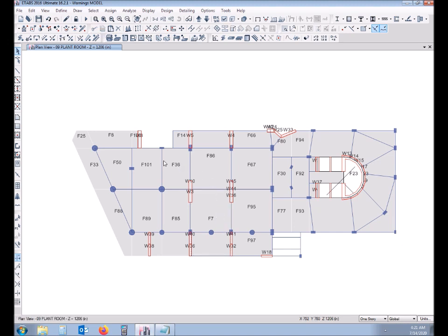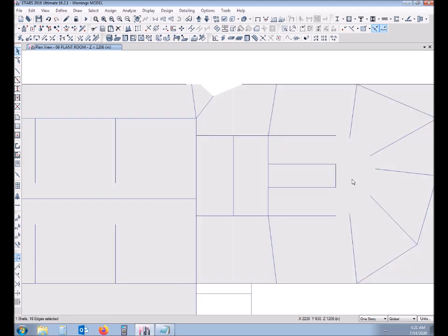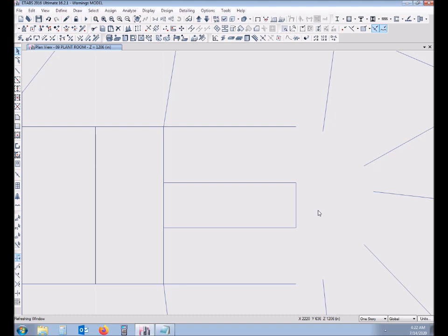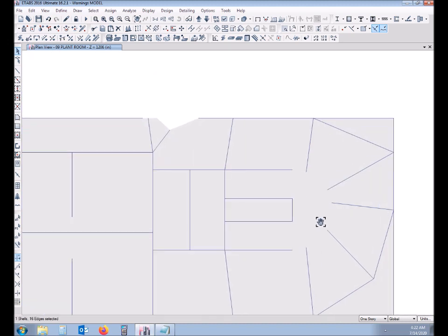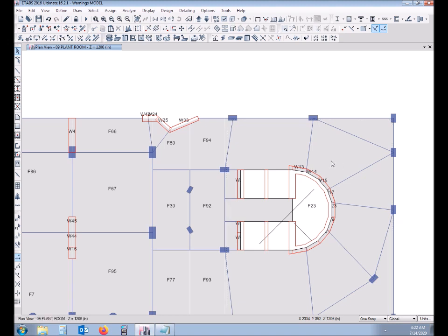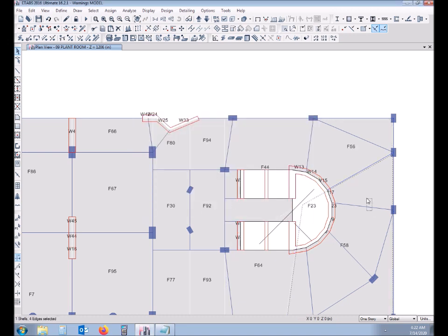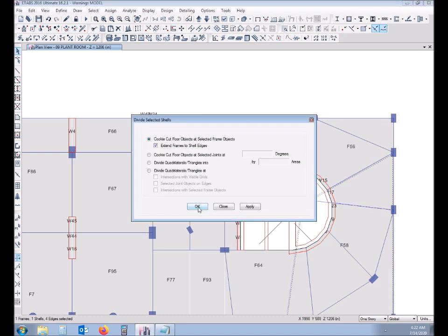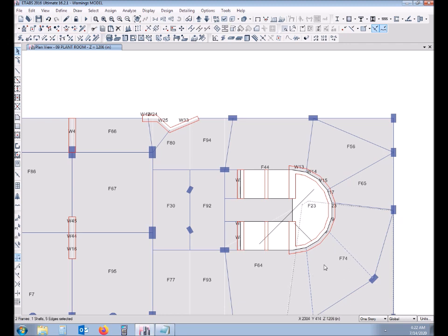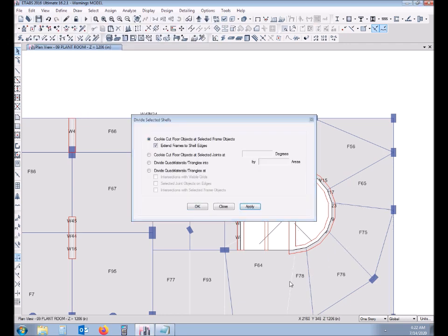So I'm going to delete this F23, which will also delete my void area, and draw it again, as I'm sure it might have been coinciding with a particular point causing the area load transfer error. I'm going to mesh the slab, which I already mentioned must be meshed, although I have selected the auto mesh option as well, but to be sure that the slab is meshed above the beam. Okay, so I just have to delete this, select this F23.